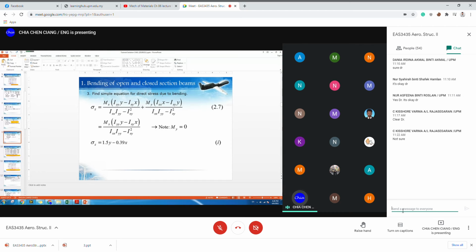But now if we see equation 2.7, should we increase Ixx alone? Or maybe not, because we don't have a moment My in this case, right? So we concentrate here. So what should we increase? Iyy, I suppose, right? We should increase Iyy. To modify Ixy is something you can do also. You can do that also.